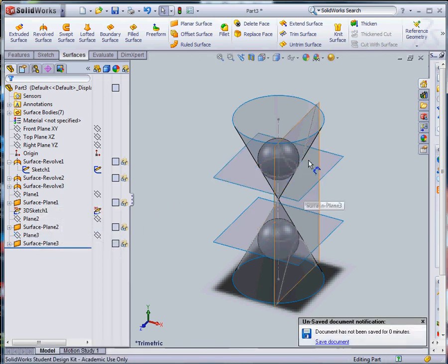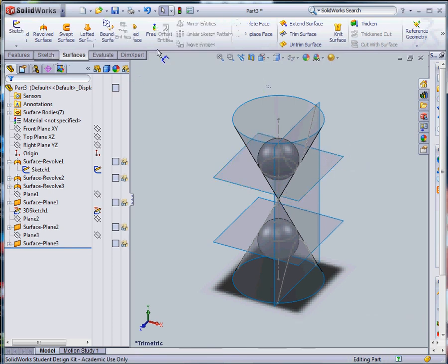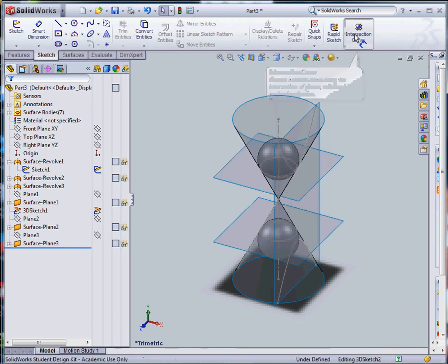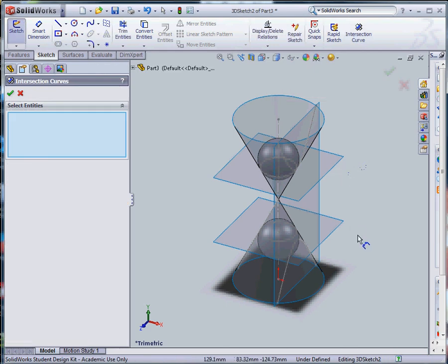Now what's next is we're going to insert our directrices. So again, we'll use the same tool as before, the intersection curve option. At this time, we want to put in the directrix for both our hyperbolas. So directrix is, as we know, the line of intersection between our sectional plane along our circle of contact and our sectional plane along our hyperbola, and the same up here.